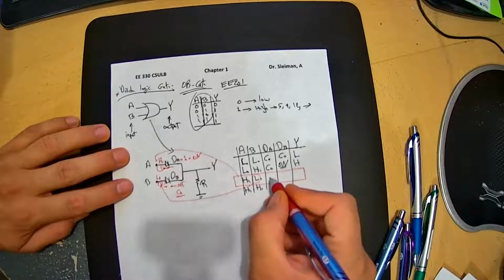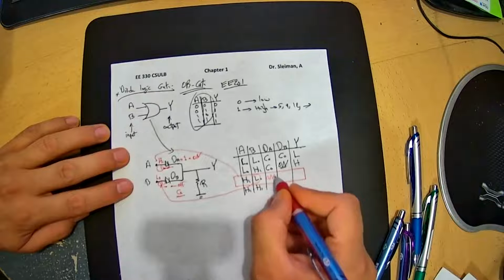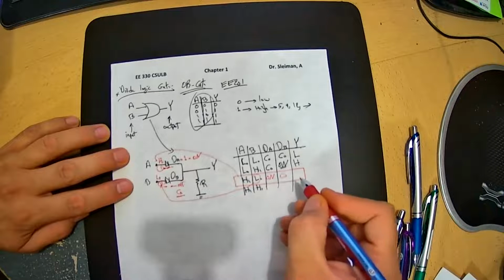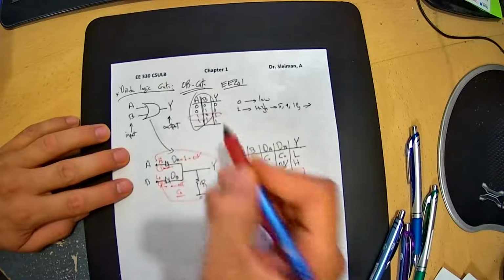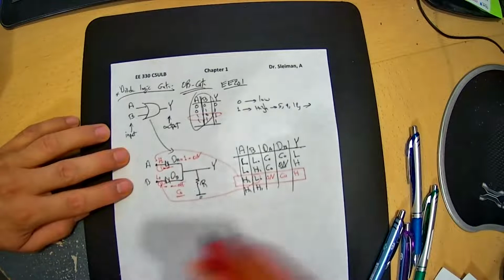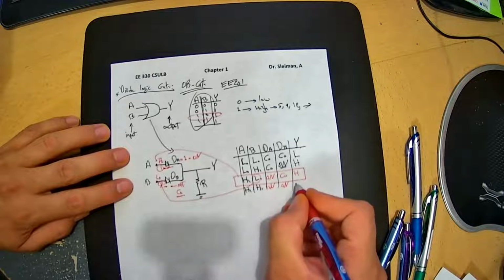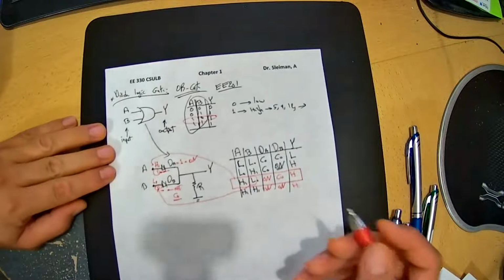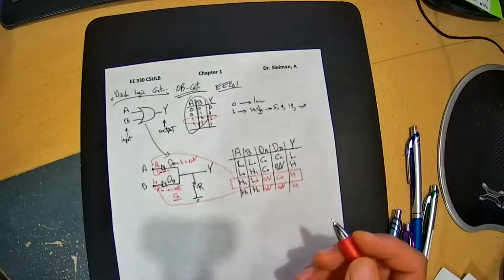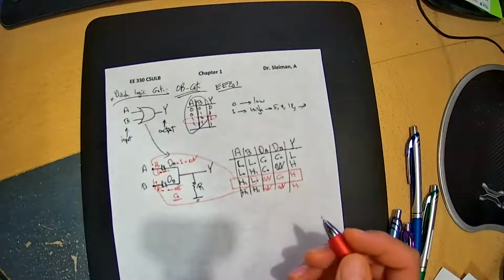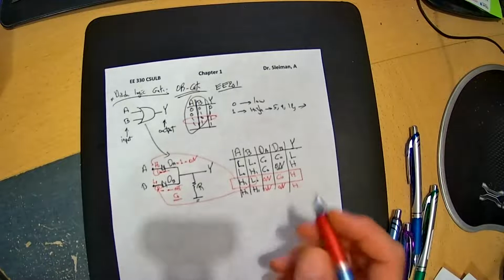So this is on and this is in cutoff, and the output will be high because, remember guys, it's an OR gate: the other one, high, will be on, and high. So this is how we introduce diode logic as an OR gate.